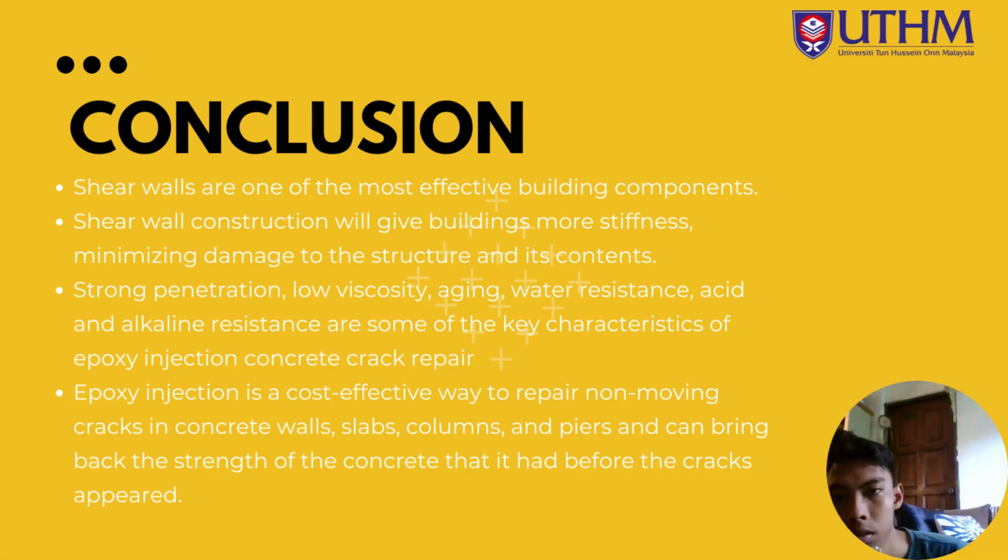As the conclusion, shear walls are one of the most effective building components. Shear wall cross-sections will give more building stiffness and minimize damage. Strong penetration, low viscosity, being water resistant, and acid and alkaline resistant are some of the key characteristics of the epoxy injection for concrete crack repair.